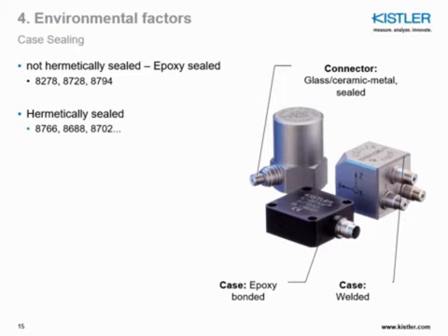If we are saying in data sheets environmentally sealed, it also means epoxy sealed. It means that the sensor case assembly is not fully welded or not welded at all, and it's more about putting it together using epoxy. In that case, you are not watertight. Once again, we are here talking about the sensor housing case only and not about the junction with the connector.